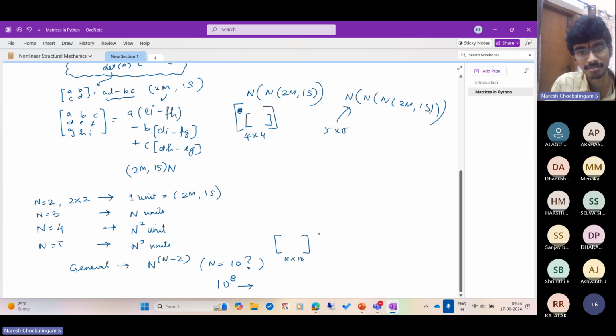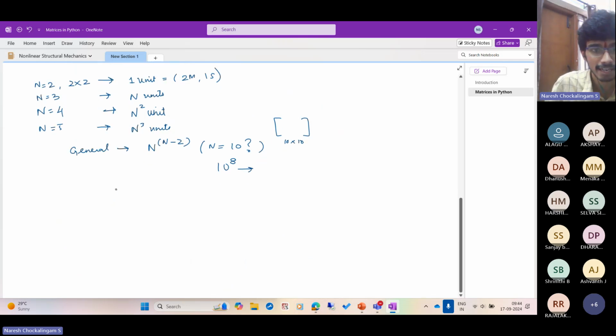When you look at real structural systems, like a real multi-story building which has thousands of beams, or you look at some analysis of a bolt, when you discretize with a large number of finite elements, the matrices that we typically get in a real finite element analysis have n of the order of 10 power. So it'll have way above 1 lakh degrees of freedom. So the number of degrees of freedom will be 1 lakh to 1 million. And imagine the cost of computing the determinant with such a large system. So it's basically not possible.